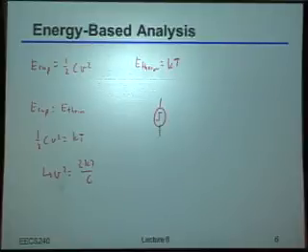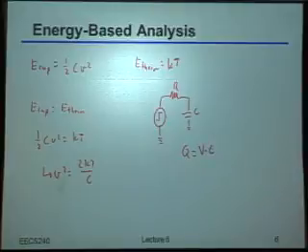you took a voltage source that basically had a step, and you asked the question of how much energy got pulled out of that voltage source to charge that capacitor, right? The simplest way to figure that out would be to say that, well, okay, the charge on the capacitor is just whatever the voltage is times the value of the capacitor, right? And the energy that came out of the source is just equal to the charge times the voltage. Well, and of course, if you do that, you'll indeed get that now you have CV squared in terms of the energy that came out of the source.